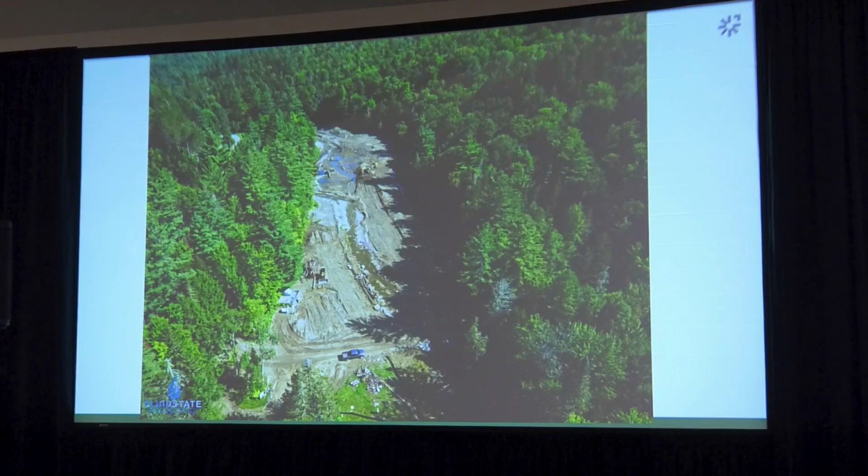You can't quite see, it's in the shadows up here, but they had a temporary crossing at the upstream portion of the site. The dam is actually just down here, out of sight around the corner. So they were phasing that lowering of the dam in small increments, removing sediment, and keeping the water clean and running through the site, not coming into their active work area for as long as possible.